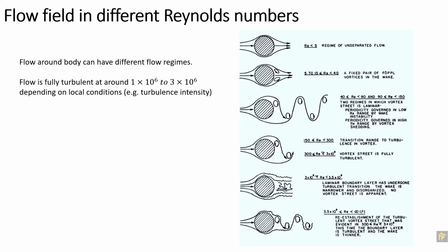And the simulations that you might have seen in some YouTube videos are mostly made in the Reynolds number range up to 150 or 200. Typically, I would be making them at 100 to 200. What you are going to see is the same vortices, but they will be alternating, from top and bottom. One time the flow will separate from the top, and the second time the flow will separate from the bottom. So you will get an alternating type of vortices. This is called a von Karman vortex street.